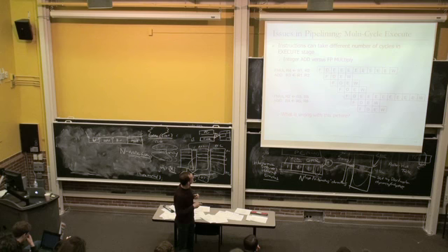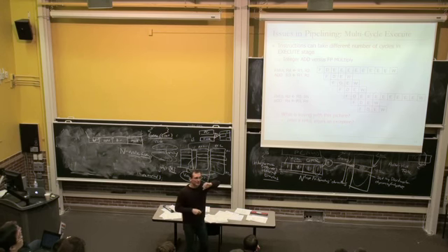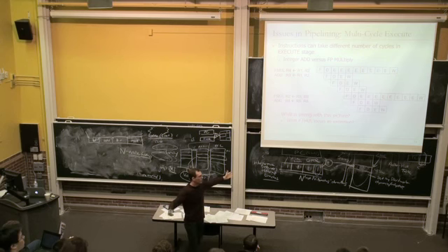Well, what's the problem with this? We've broken the sequential semantics. We shouldn't really write to the register file right here. And there are other problems actually. If this floating point multiply incurs an exception somewhere, let's say you're doing some floating point multiplication or a store, and you figured out there's an exceptional condition. If you know floating point, maybe you figure out that there's a divide by 0. Maybe the result is not a number at that point because it cannot be represented with the floating point format you have. And you figure out the exception right here.